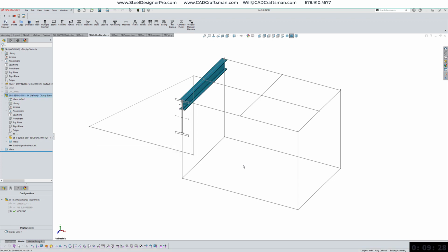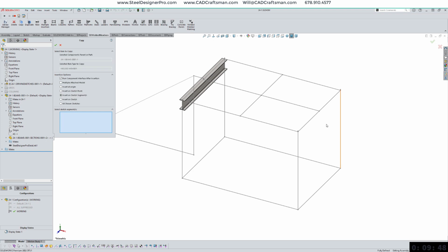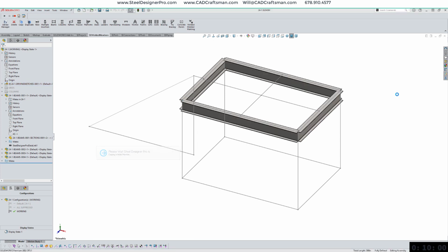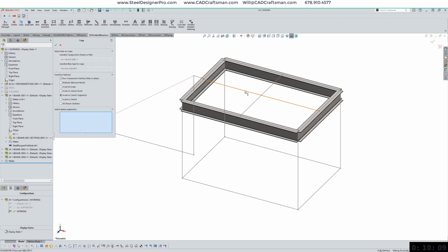When changing section sizes, SOLIDWORKS sometimes adds or shows the weldment profile sketches, which can be deleted or hidden as needed. I will use SD Welded Members Copy function to add the remainder of the perimeter beams. I will use Copy to create the first interior beam member.